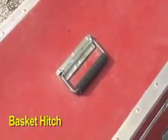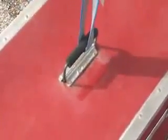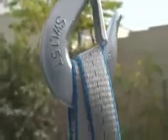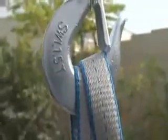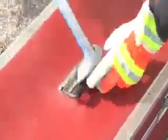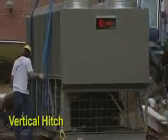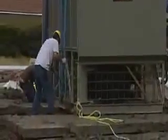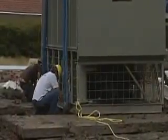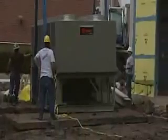The basket hitch is the most common type of hitch used, and it usually provides the largest workload limit. It is a simple hitch made by placing the sling around the load and attaching both ends to the hook. With a choker hitch, the sling is wrapped around the load once and then through the shackle on the other side. It is pulled tight and attached to the hook. The vertical hitch is used with loads having lifting attachments. One end of the sling is connected to the hook and the other directly to the load lifting attachment. This vertical hitch only has approximately 50% of the basket hitch workload capacity.